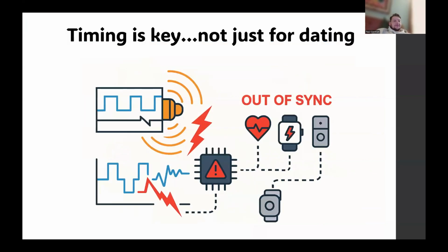So let's get into the consequences. To see why this really matters, let's consider a simple example. Imagine a medical wearable or implantable device where a high speed digital line was routed across a split in the ground plane. The return current can't follow directly beneath the trace, so it detours around the split, forming a large loop. Under normal operations, everything might seem fine until a high current motor nearby switches on and its rapid current change from an AC source produces a magnetic field spike. And because our loop is now effectively an antenna, Faraday's law tells us it'll pick up an induced voltage.